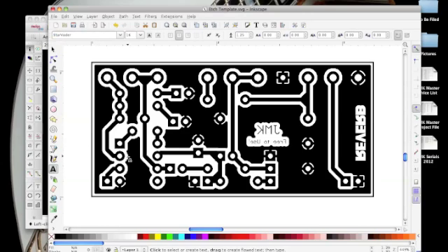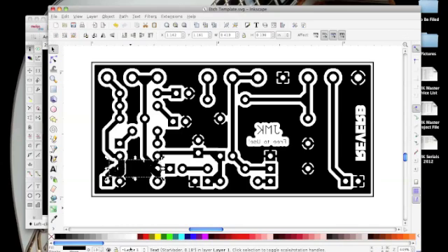I use my text tool here. I make my text white. Let's see if this works here. JMK. Oh, it didn't work. Well, let's see here. Just make it white. Now I select it white. Flip it around. Change the size. 0.1 inch. Look at that. I've got a little JMK there. I can stick in there anywhere I want. Select your font. You can also import images if they're black and white. You can do all that sort of stuff. Great stuff.